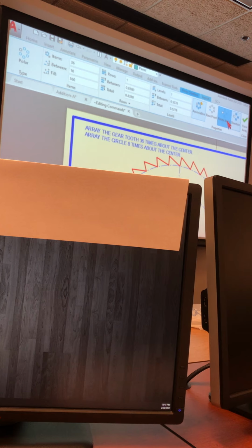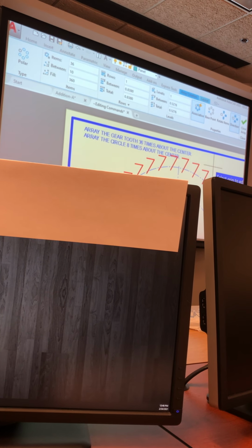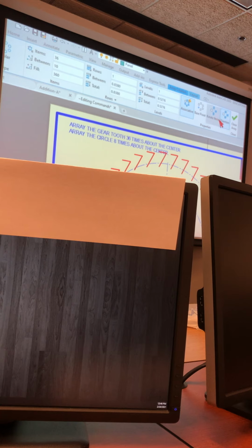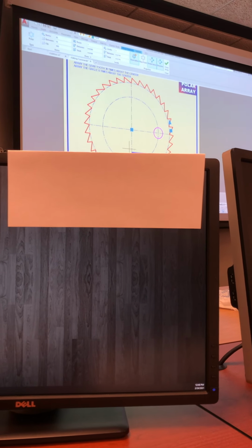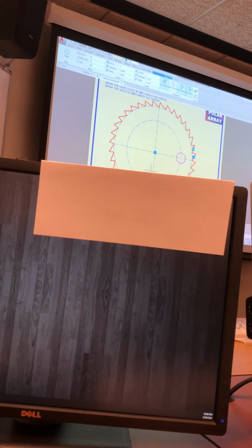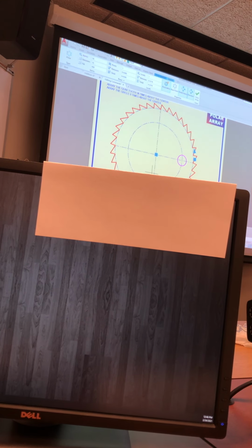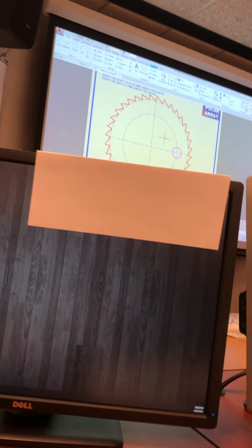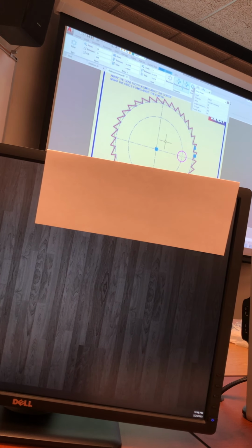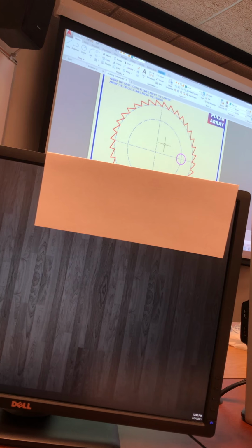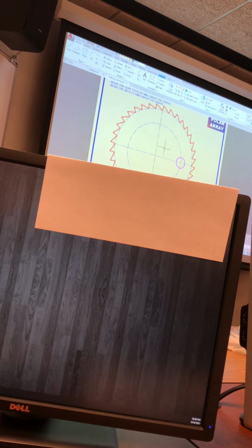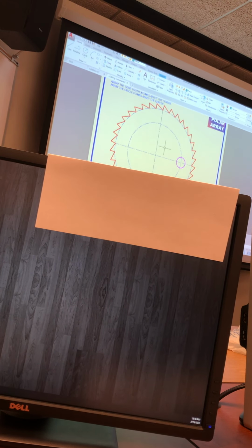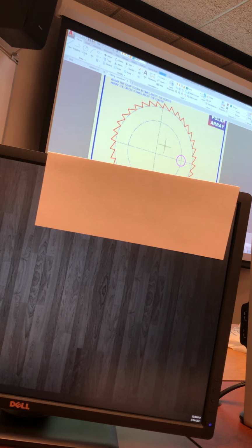Now items can be rotated or not rotated. Those teeth definitely need to be rotated. And it is also a group. So later I can click on it and modify it. All right. Questions about polar array? Number of items, give it a center point, and go for it.